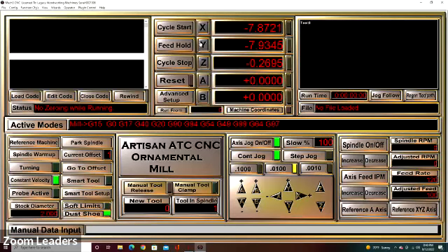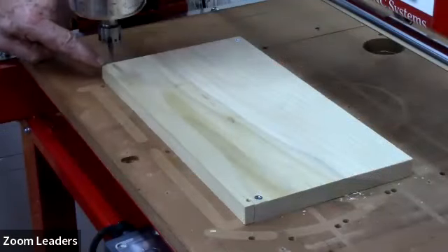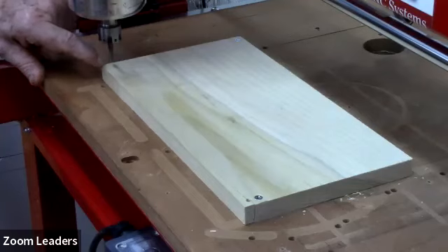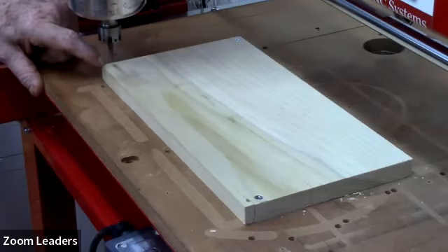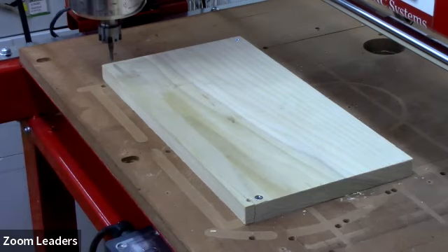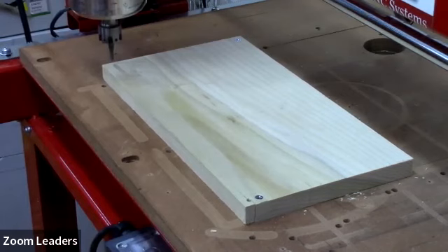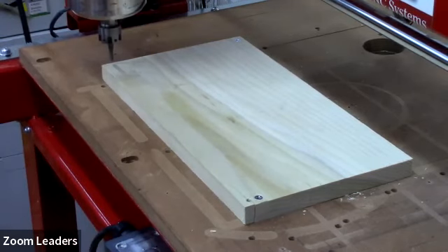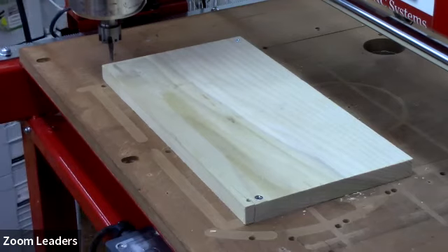Anybody want to speak? That board can go anywhere on the spoil board because you're telling the machine where that corner is. What I'm saying is my reference point for the project that I'm doing is right there. Right, but that part could be anywhere on the spoil board because you're manually setting where that zero is. Exactly, exactly. And two things, okay, there are machine coordinates. That's the absolute coordinate for the machine. There's the job coordinate, which is what he's trying to separate now, where the zero is in physical space.